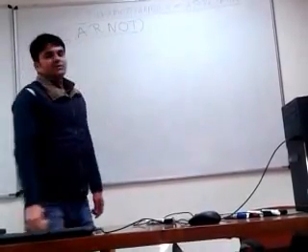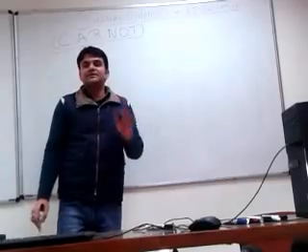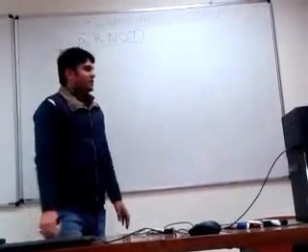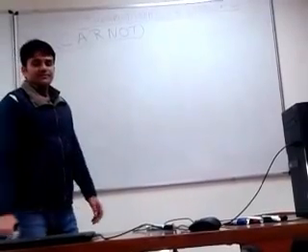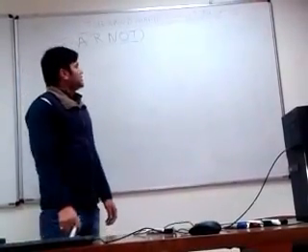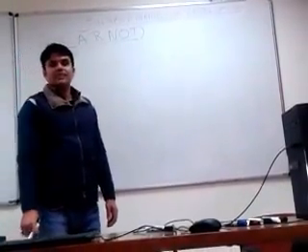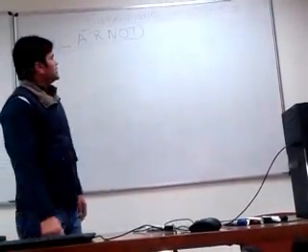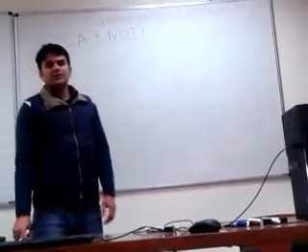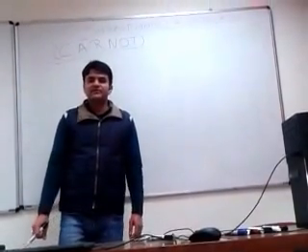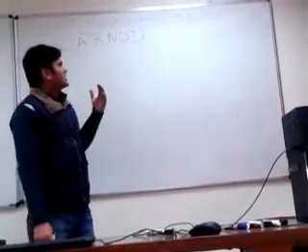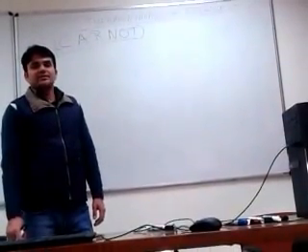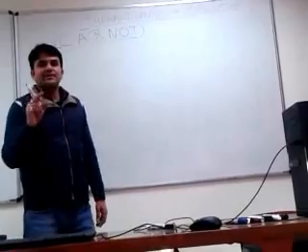The Carnot cycle is completely an imaginary cycle, and it is not practical to run an engine on a Carnot cycle. It was given by Carnot in 1824, and the use of the Carnot cycle is that no other cycle will give more efficiency than the Carnot cycle working between the same temperature limit. I am repeating, same temperature limit.